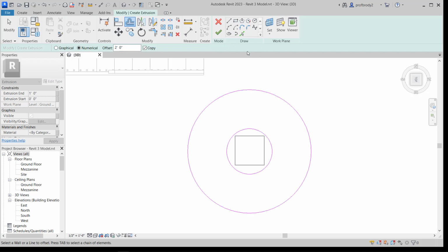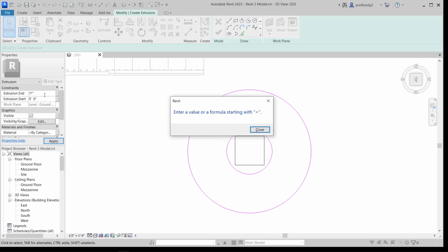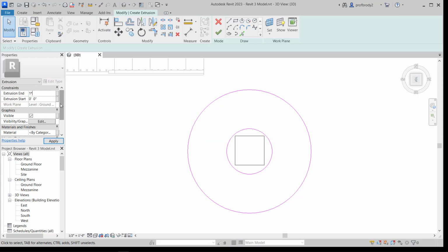I can also draw with any of these objects just so long as they form a complete loop, and any interior surface also forms a complete loop. The other thing about creating these extrusions is they have a dimension, how high or how horizontal they're going to go. So I could even just set this to 18 inches, which is probably about the typical height for a bench.